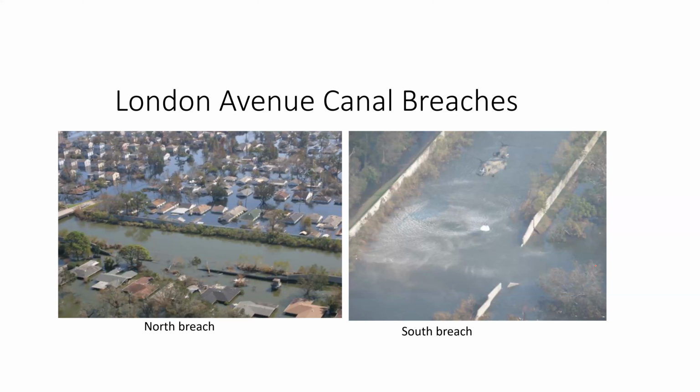What is seepage? Exactly the same thing. It goes from high point to low point, and soil gives you the resistance through the hydraulic conductivity. So it has some loss. Every unit length it travels, it has some loss of pressure. So it goes from high pressure to low pressure, right?